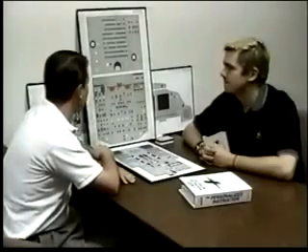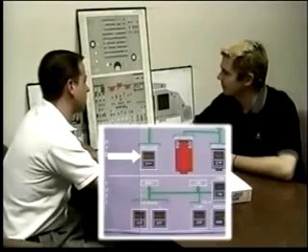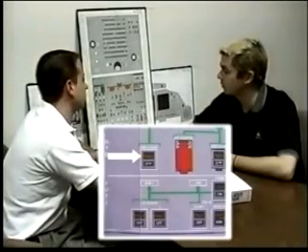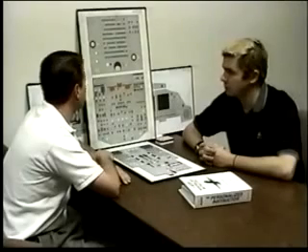4 conditions for a fault light on engine 1 pump. 3 are associated with the reservoir. What are those 3? A low air reservoir pressure, low quantity, and over temperature.